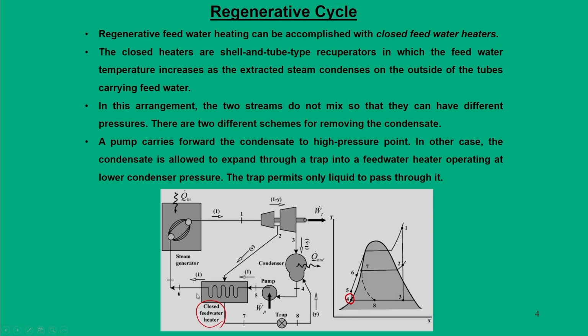So, essentially we do this dual load, and through this heating process the steam will get condensed and again be trapped in the liquid mode and go back to the condenser. So, this is the concept of tapping the water or steam from some of the end of the turbine and reusing its heat for heating the water.